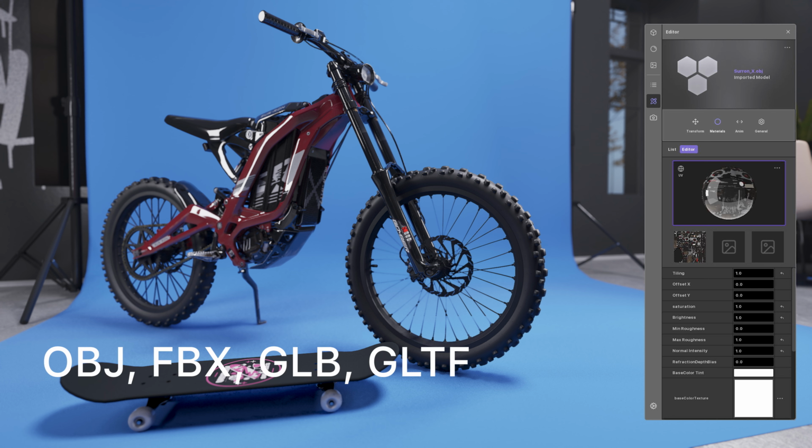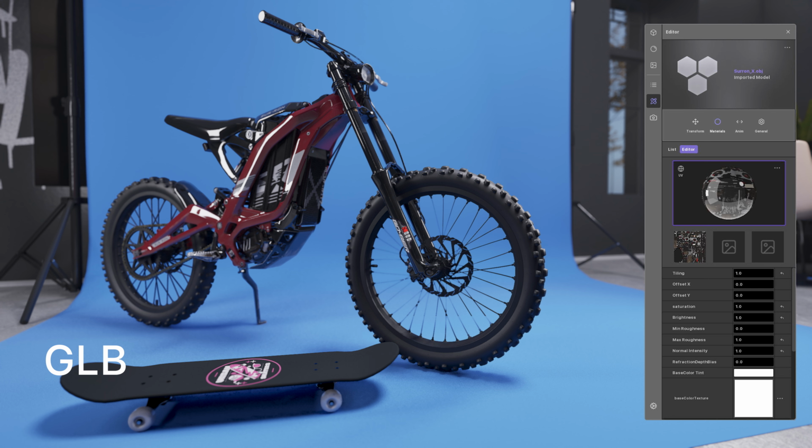Supported formats are OBJ, FBX, GLB, and GLTF. We recommend using the GLB format because it's a modern format commonly used in real-time engines. GLB packs geometry, materials, and textures into a single binary file, unlike OBJ or FBX, which store these separately. GLB files also load faster and are easier to work with.